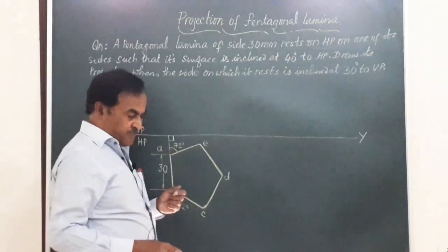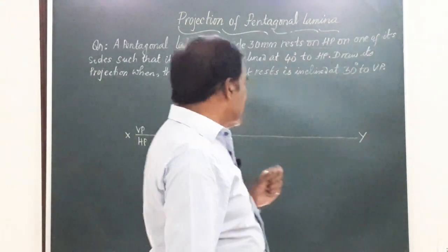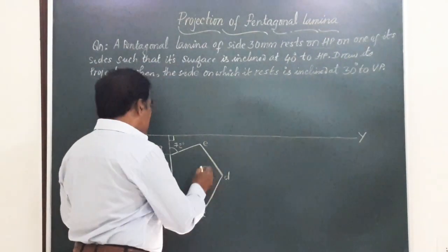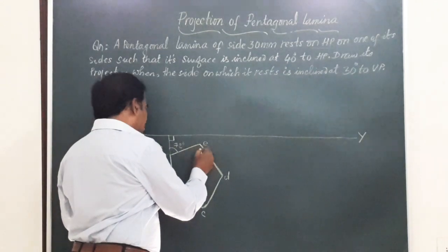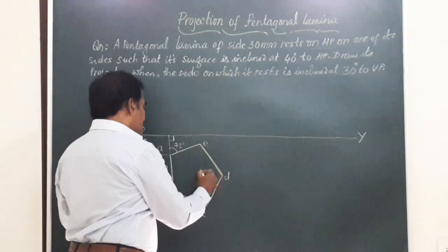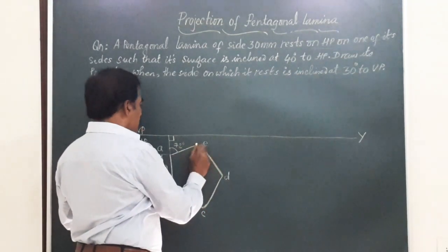and obtain the front view. Friends, remember, generally the students go wrong while constructing this figure, and if the figure is not properly constructed, then if you are drawing a vertical line through C, it should and must pass through that E. So, if the construction is not correct, you get a separate line through C, separate line through E.